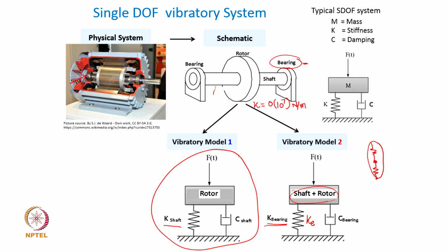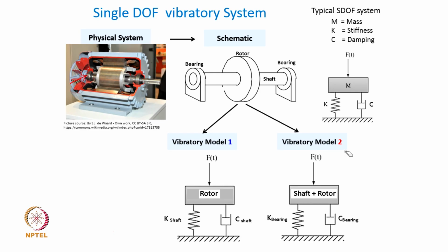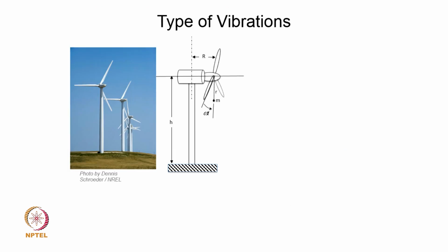Now, in addition to this discussion, I would like to also discuss a little about what kind of vibration analysis that we can perform, or in the sense of types of vibrations or the modes of vibration, right. So, the example that we have been discussing of a wind turbine nacelle sitting on the column like this, we have seen that there will be a bending moment acting on it, there will be a twisting moment acting around the axis of the column, and then as this bladed rotor rotates, there would be a fluctuating vertical force which will act axially, and longitudinal excitation will excite the column.